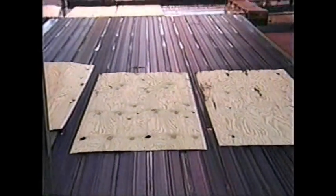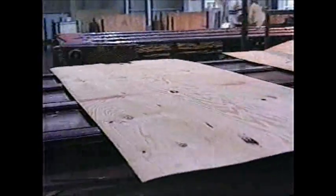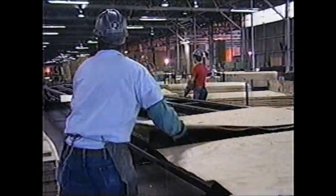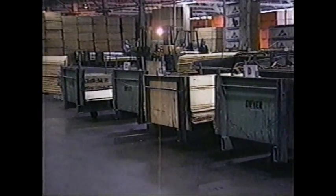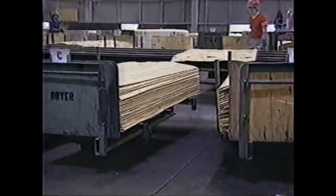While most of the veneer is dried to specification, all the veneer passes under a moisture content monitor. Any veneer exceeding moisture content limits is automatically marked with a red line and is pulled into a bin for re-drying. As the dried veneer moves along, it is graded and pulled from the line and placed on piles of similarly graded veneer.